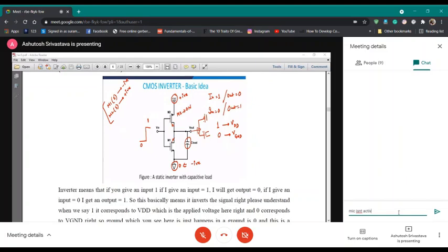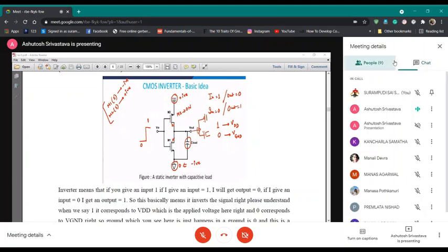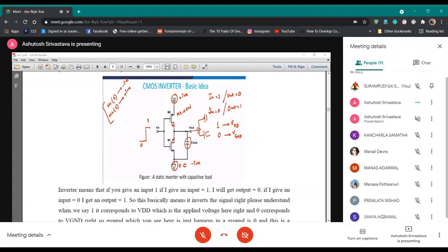That is post fabrication. Correct. So if you have the fourth terminal, if you give the voltage, it will change the overall threshold voltage. So that is once you have, when you say post fabrication, it means when your chip is already ready.